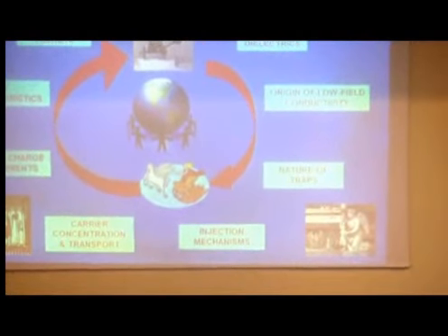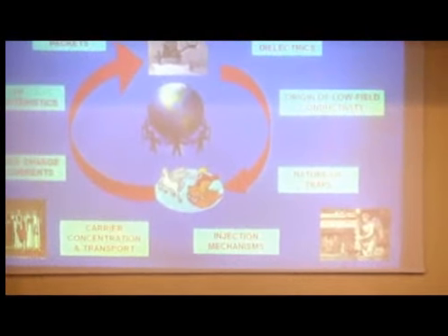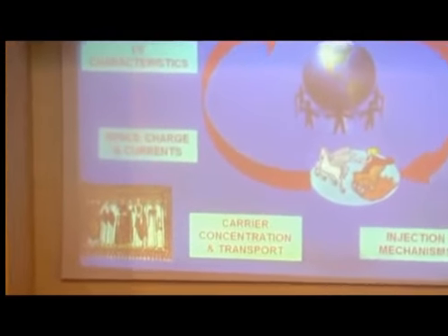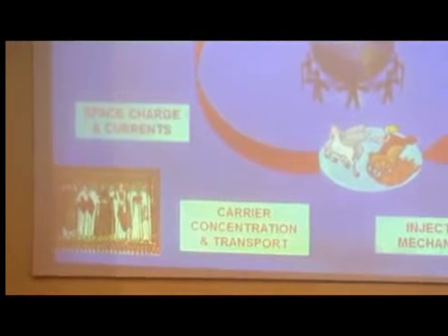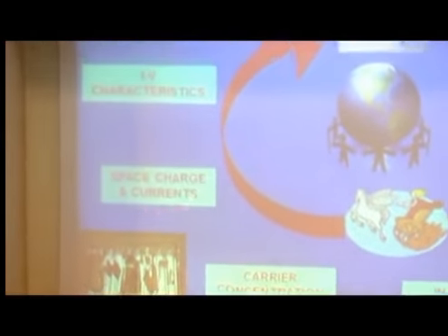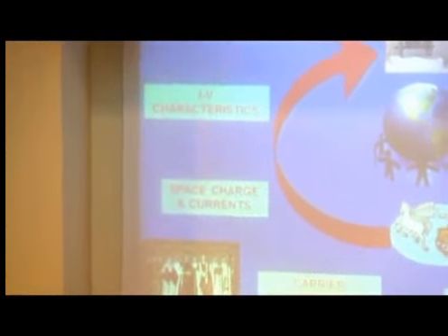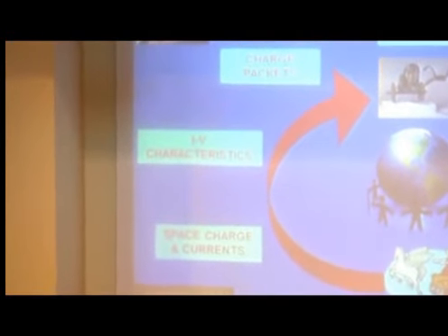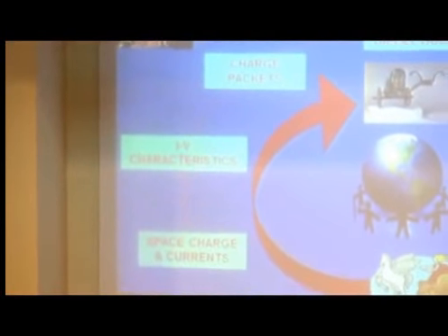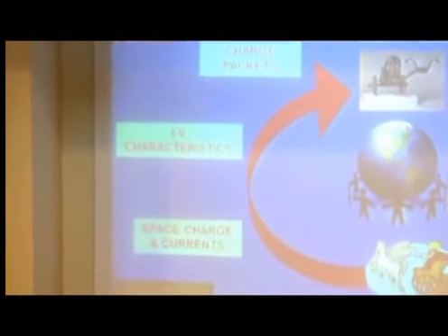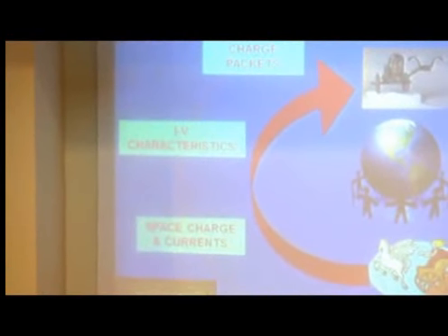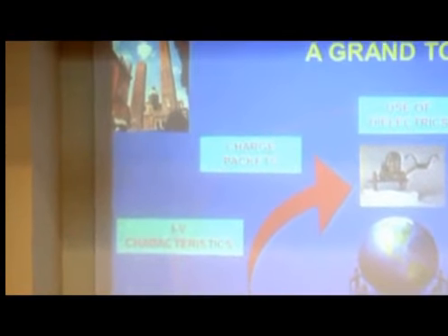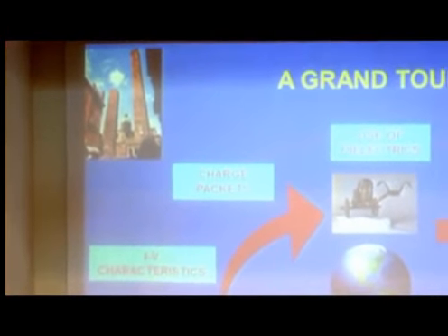As we go towards high field effects, we've got to start looking at injection mechanisms, carrier concentration and transport, the effect of high fields on these properties, and that will start to bring us over to the effect of space charge on the current voltage characteristics. We'll move over from formal theoretical ideas about this property to reality and some of the recent calculations. Finally, I'll end up talking a little bit about charge packets.